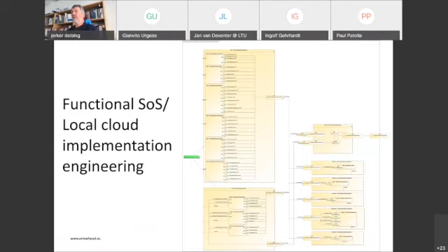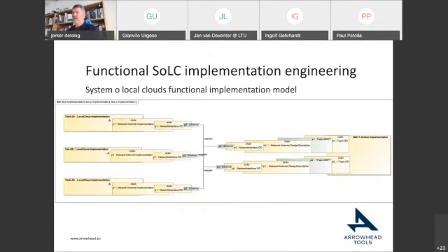And this now constitutes one local cloud. We previously talked about having multiple of these tank setups, and for whatever reason now I just made 3 of them. So these are 3 different local clouds: tank 2A, 2B, and tank 3C in a kind of imagined factory. And they are talking to the MQTT broker to enable information to flow outside of these local clouds to those who have the rights to access that.